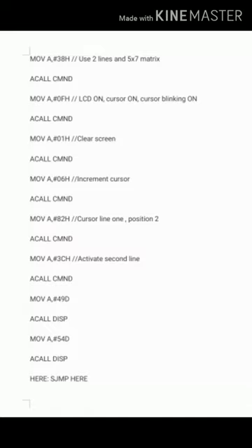What we are supposed to do, I have already explained to you. What we need to do is simply send the data to an LCD unit, and once we send the data to the LCD unit, the microcontroller should also let the LCD know whether the data sent is a command or data to be displayed, right?